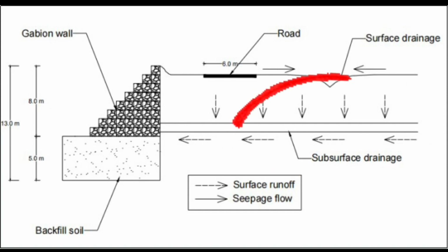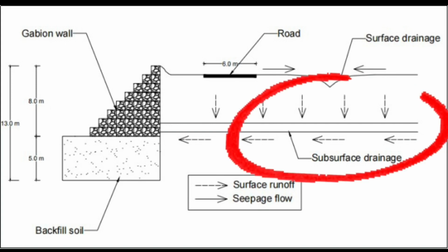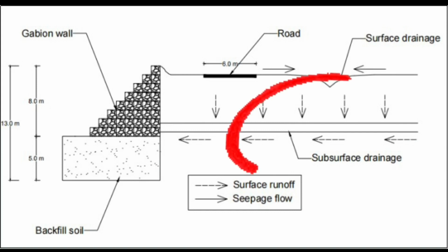For the subsurface drainage, horizontal drain holes were utilized to discharge groundwater flowing down inside of a slope and groundwater flowing out of a slope. Casing pipes are typically made of hard polyvinyl chloride pipes, also known as PVC, or gas pipes that have an internal diameter of more than 40 mm.